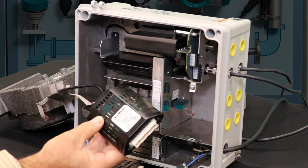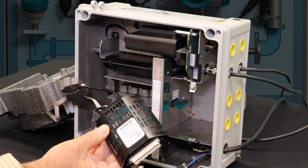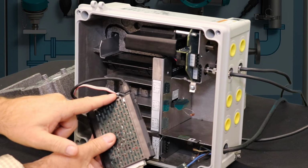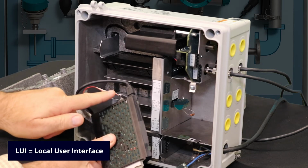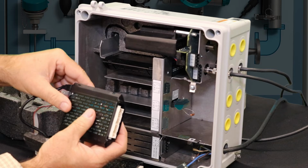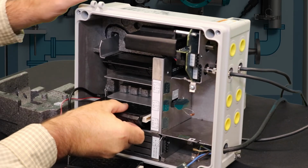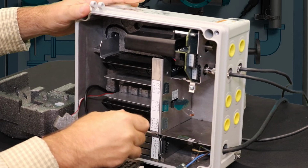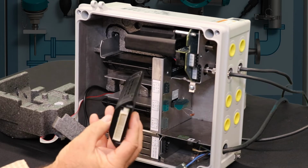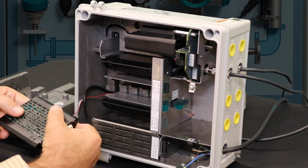Now I'll explain what these cassettes are. This is the transmitter cassette, and this also has the functionality of either HART or Modbus. It has the cable where the LUI or the display is plugged into, and a small extension for the USB connection. So I'll plug this back in. This is the I/O cassette, and the functionality will vary based on the order code for the meter. I'll plug this one back in.